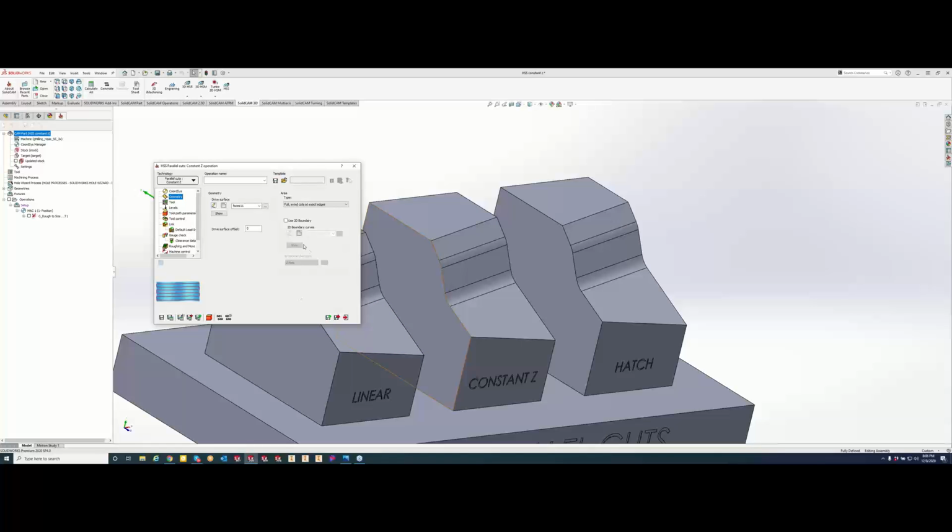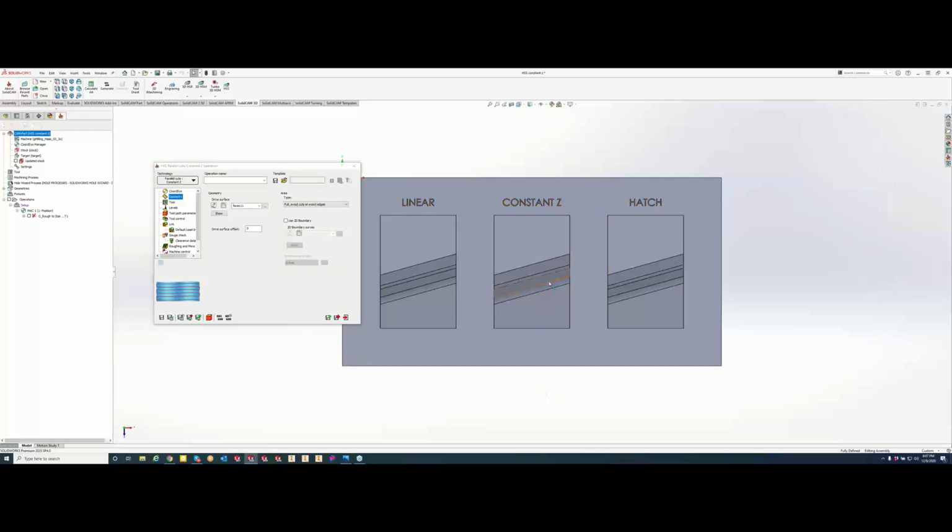Okay. Now, stepping down here, we can create a boundary. So what this boundary will do is, maybe we just want to focus on a specific area. What you guys can do is throw a 2D sketch on there and keep it contained. Like if we were to do a normal 2 view here, let's say we just wanted to keep it contained to a circle area, we could draw a sketch on there and it would trim off the tool path outside of that circle for you.